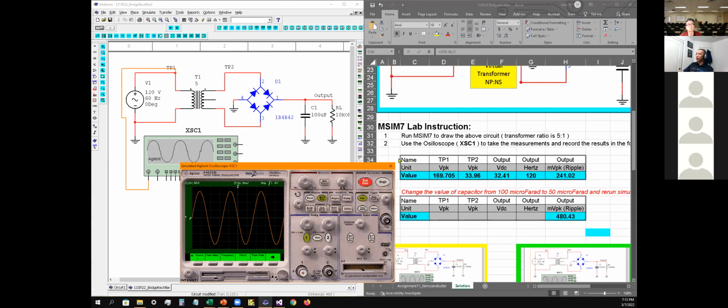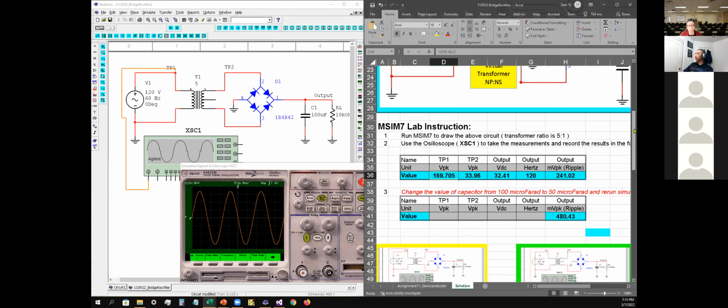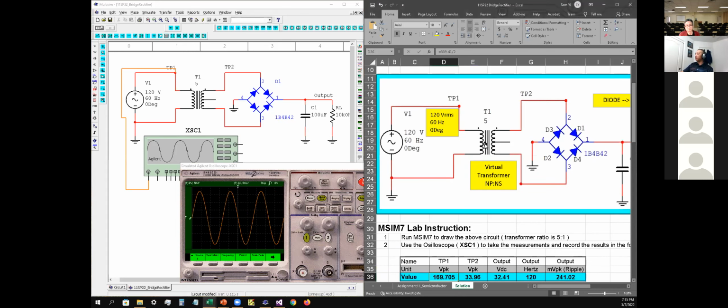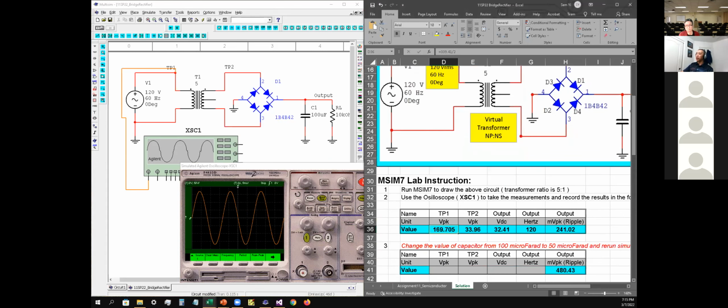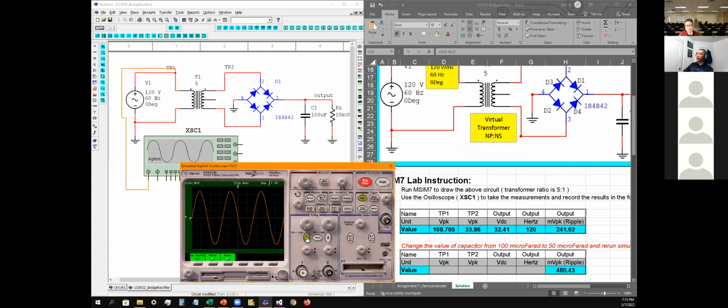And then if you want to change the source, like Mr. Pham was talking about earlier, either you use the DC coupling or AC coupling. What you want to do is click on the source, which is channel 1, and that brings up the sub menu. So you've got the coupling right here. So you click on that. Now you can choose ground coupling, DC coupling, or AC coupling. Okay, depending on what you want to look at.